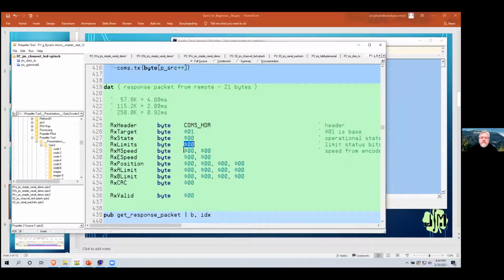This is the motor speed. The particular motor speed controller that we're using uses a signed byte. Or it's a direction plus speed. So it's 0 to 255 for speed plus direction. So we just send it as 2 bytes. So this is the motor speed. This is the encoder speed. Because this is a P1, I wrote an encoder object that will give us position and velocity from the encoder object. And then these are position values.